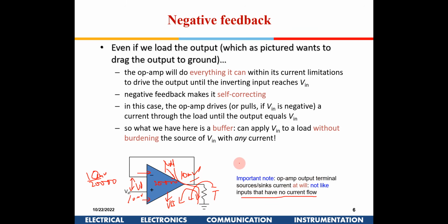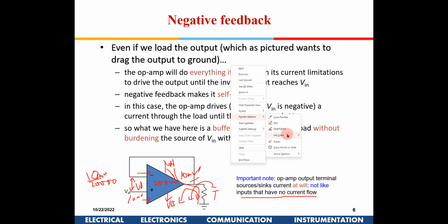Sir, I have one more question on this same diagram. Is there any reason why we don't give this negative feedback to the positive terminal? Then it will become positive feedback, and if you give positive feedback, it will work like a comparator only. It will be either VDD or ground.